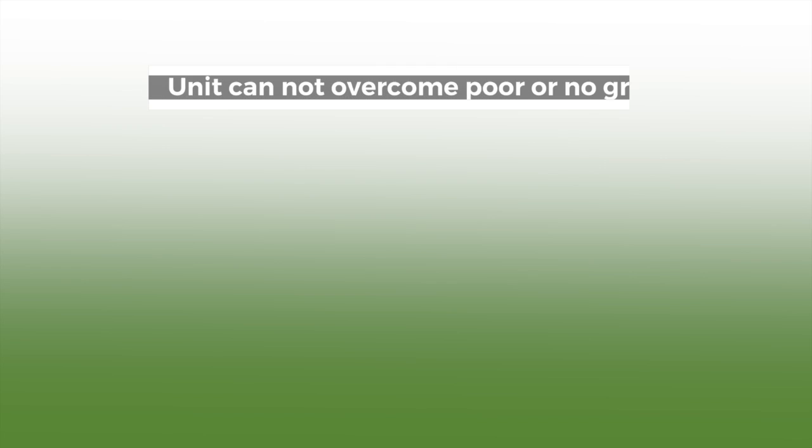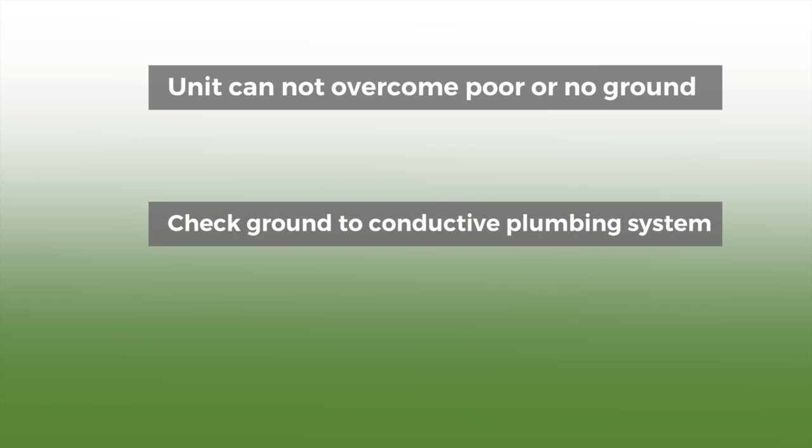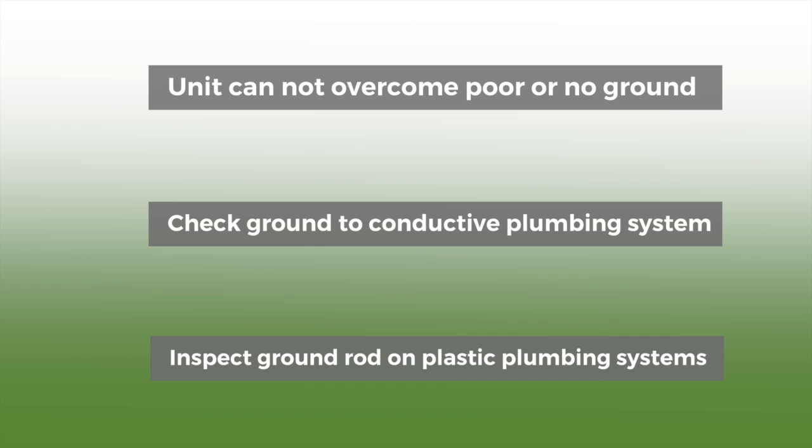Note, unit cannot overcome extremely poor ground or no ground. Check ground connection to conductive plumbing system and inspect for properly installed ground rod on plastic plumbing systems. If not properly grounded, an electrician will be required to resolve the problem.